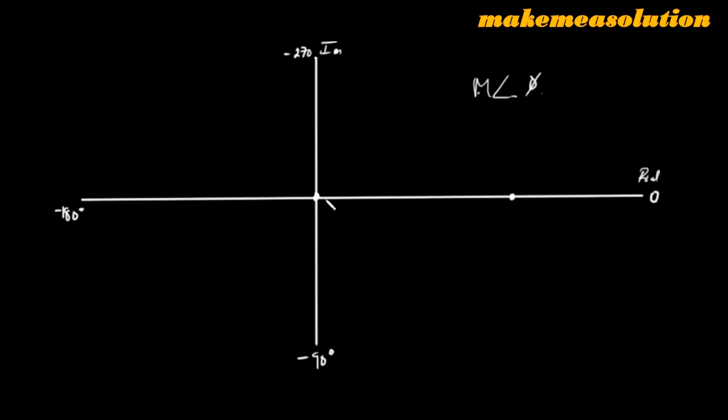Okay, so it's just going to rest on this place. So I can simply say that k is here. Okay, it's on the 0 degrees line, and let's say from here to here is k. So when ω tends to 0, our amplitude is k and our phase is 0 degrees.